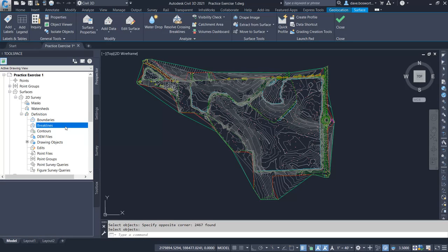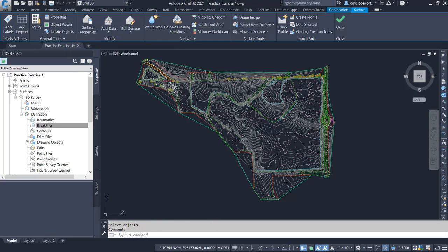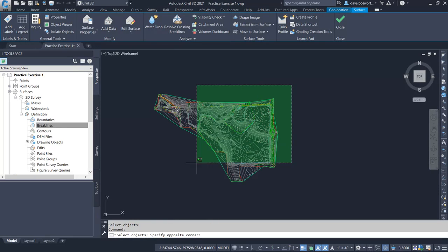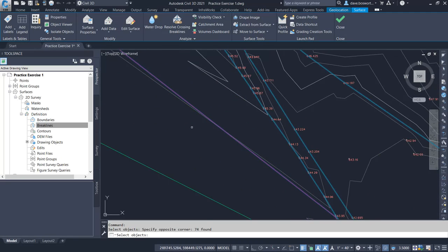Because these polylines are in 2D, they'll be proximity break lines. We'll add them as a crossing again, but before applying the selection, type R followed by Enter on the command line and remove the red boundary polyline from the selection.